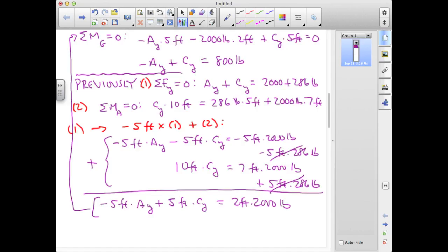That is, when we replace two force component and one moment equation with one force component and two moment equations, it simply represents a different linear combination of the equilibrium equations. We could similarly eliminate the force component equations entirely and impose three moment equations as long as the 3 points about which we take moments don't all lie on the same line.